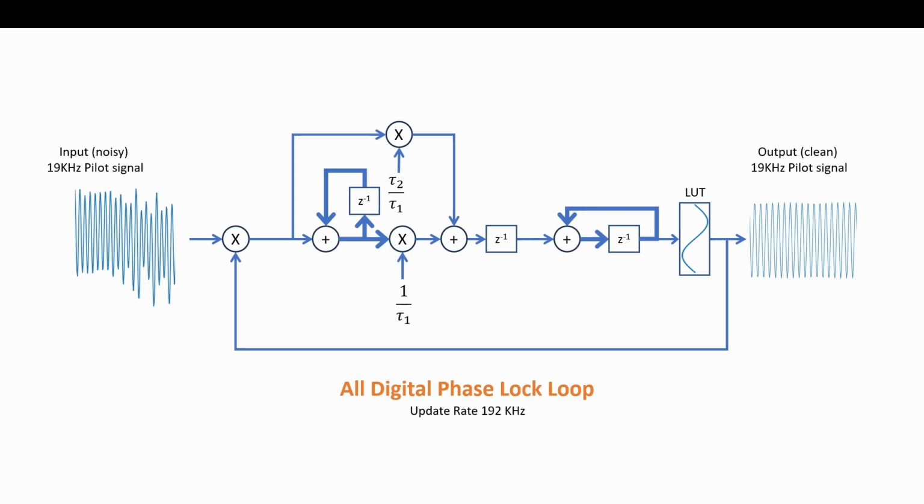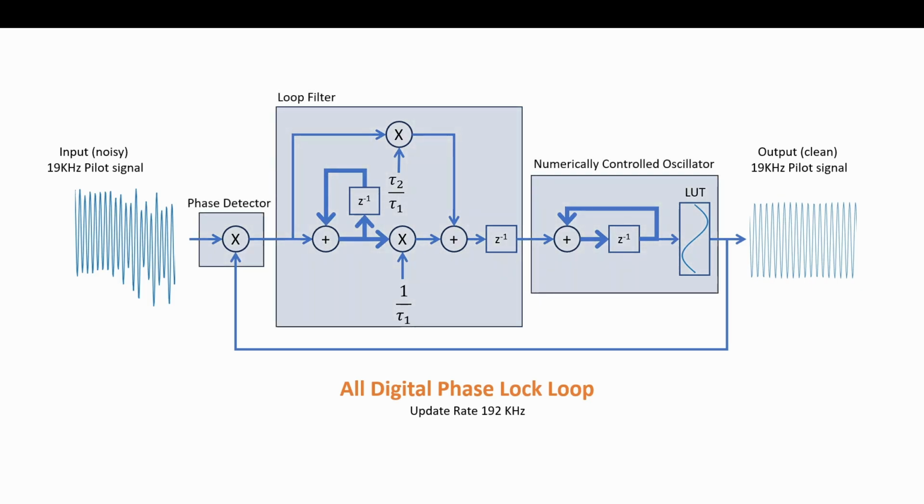As a block, I'm showing you something that will work just like the VCO, where we can change the digital value, and it will produce faster or slower sine waves depending on that value directly. It's going to be directly proportional, the frequency of it, directly proportional to the value of that input. So that's showing you those 3 components.